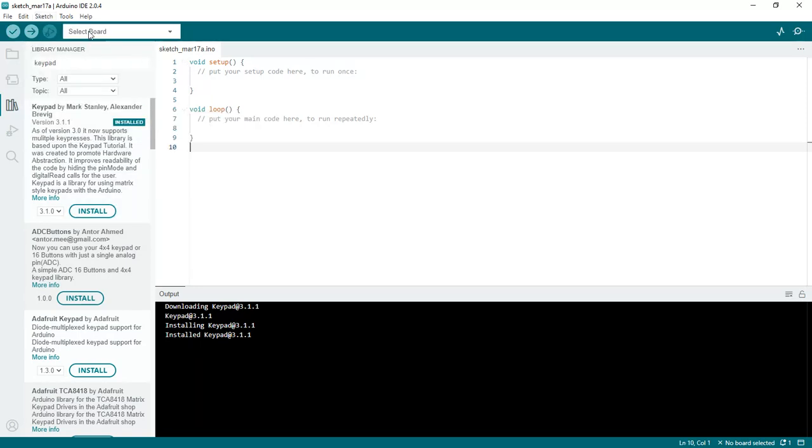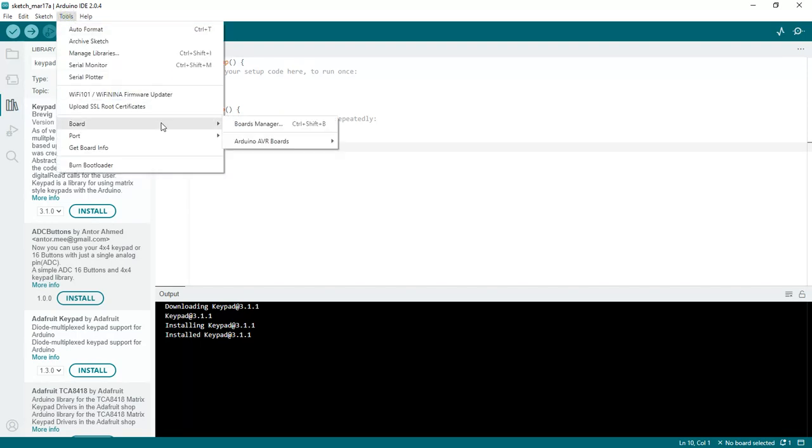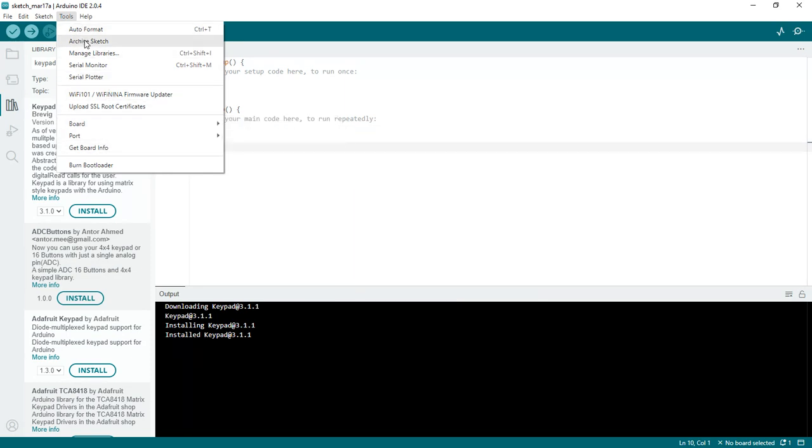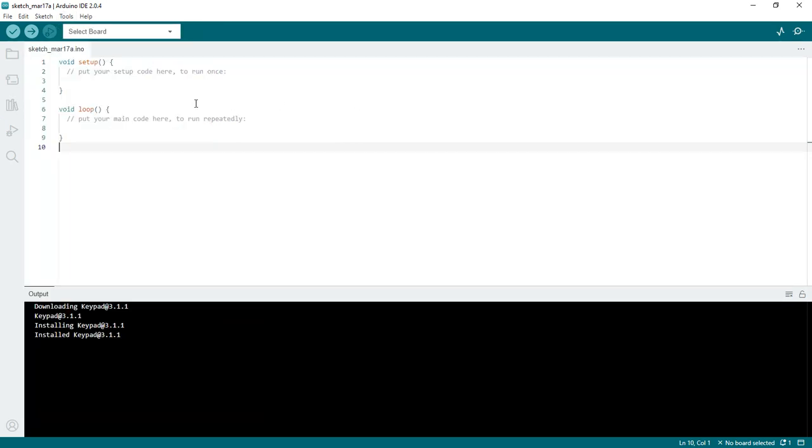Now, board selection is also important for every program. Whether you are dealing with the Uno board, Mega board, or even ESP boards, which are boards with inbuilt Wi-Fi support like NodeMCU, ESP8266, all these libraries you also need to take out. For boards also you need to manage your libraries. For any kind of application on the respective boards, you need to install the libraries compulsorily.